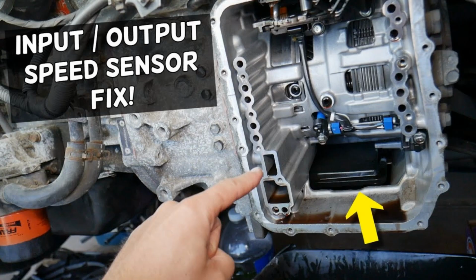Output shaft speed sensor. Some vehicles use a plastic gear at the end of the OSS sensor. Remove the OSS sensor and check the condition of the pinion to determine if any teeth are missing or worn. Replace the pinion if necessary. Check the wiring harness for possible signs of damaged cables or loose connections.